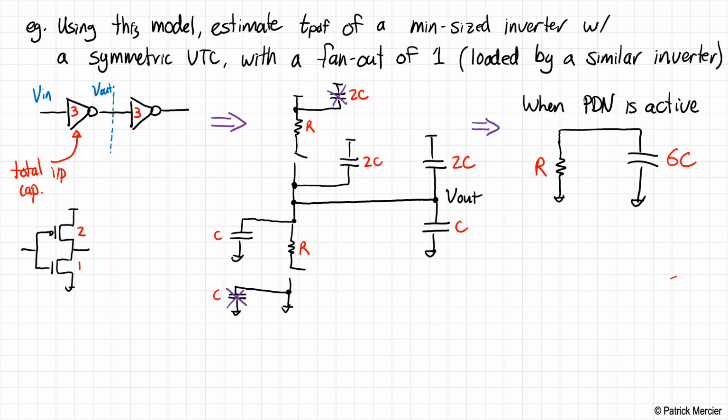So when that switch turns on for the pull-down network, we're going to have some current that discharges from the capacitor through that resistor. We can go ahead and plot what that looks like. It'll look just like what we plotted earlier. So we have V out versus T. We started at VDD, and then we had an exponential decay function. That's not totally exponential looking. Let me try that again. That's a little bit better.